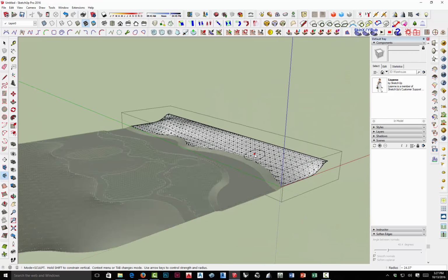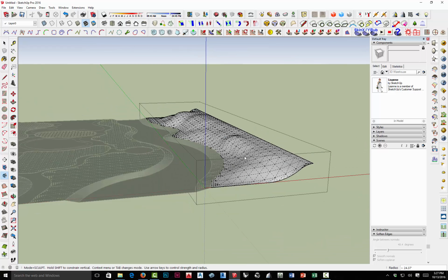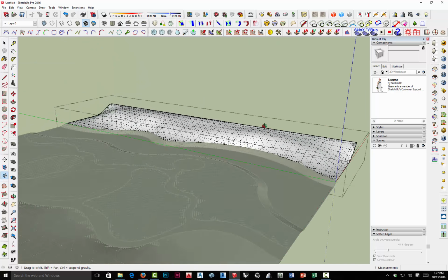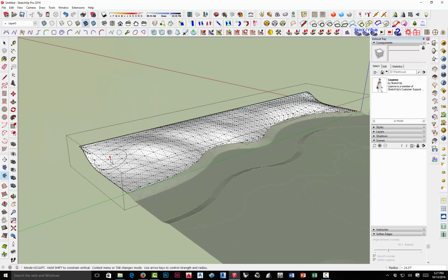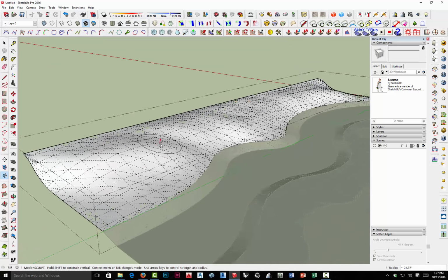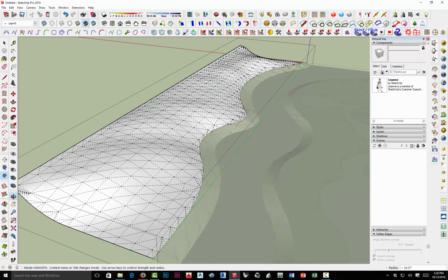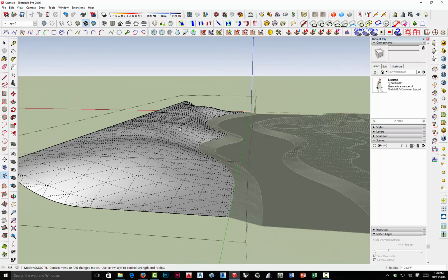Again, it's a great visual way to create and adjust landforms, just like you were modeling it with clay and sculpting it, which you've all done before. Okay, so let's just go through how you do this. Totally up to you. Once you've got it kind of set, if you want to smooth it out a little bit, you can right click and choose smooth. And again, the effect is controlled and it just goes in and blends that. You can see it with the hidden geometry on. You can see how it kind of softens that a little bit, spreads things out. Really does a nice job of sculpting organic forms, and in this case, landform. Best grading tool ever.